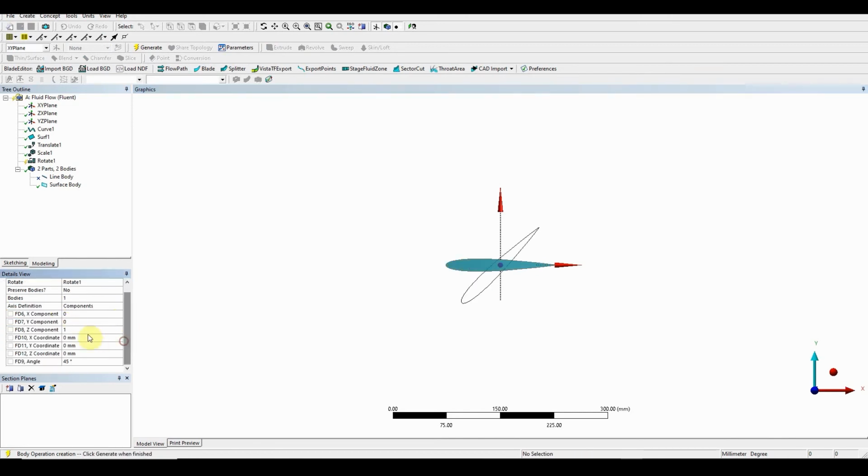Now you can see here it's gone the downward direction, because x equals +1, so if we put x equals -1, it goes in the right direction, and then we can put 0 degrees here and then generate. Now I'm using this at the moment because remember that I said in the assignment brief that once the angle changes, the position of your line rakes will also change as well. So you have to do a variety of line rakes.